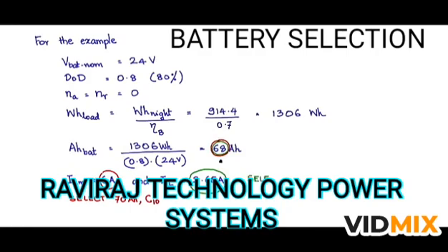This will result in selection of a battery of 70 ampere hours and C20. C20 will give approximately 3.5 amps, which is still much greater than 2.65 amp average, and therefore even this will work, but at maximum current discharge, the maximum current discharge 6 amps will be more than the C20 value, and therefore there can be slight loss in capacity. But if that is permissible, then it may be advantageous to go for this because it is definitely